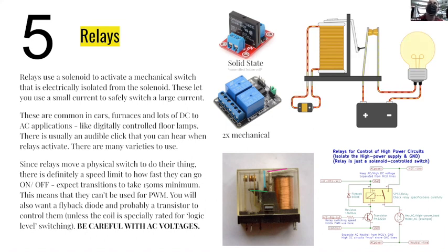And I love this GIF. When you turn on the solenoid, it pulls this little lever, which sort of jimmies around and then pushes these two contacts together. So this little teeny tiny battery, you can sort of see the analogy, is able to control this larger battery, this larger circuit, without really being in direct electrical contact. So you can switch on and off high power things with relatively low power circuits.